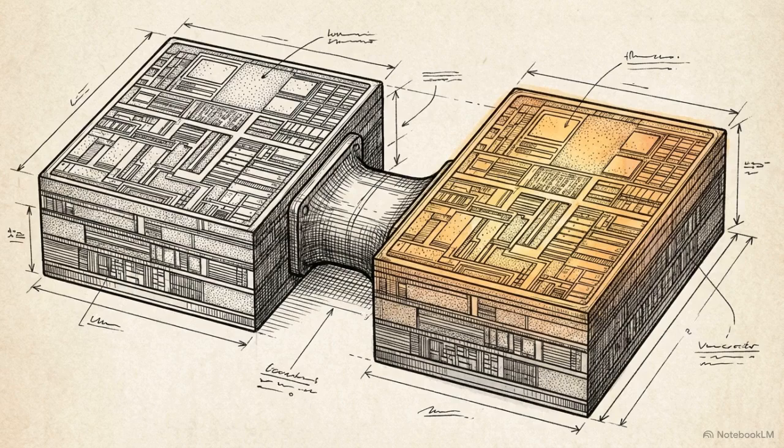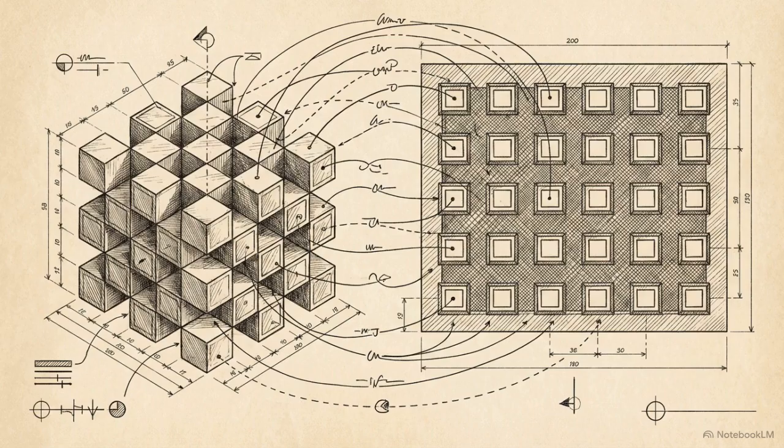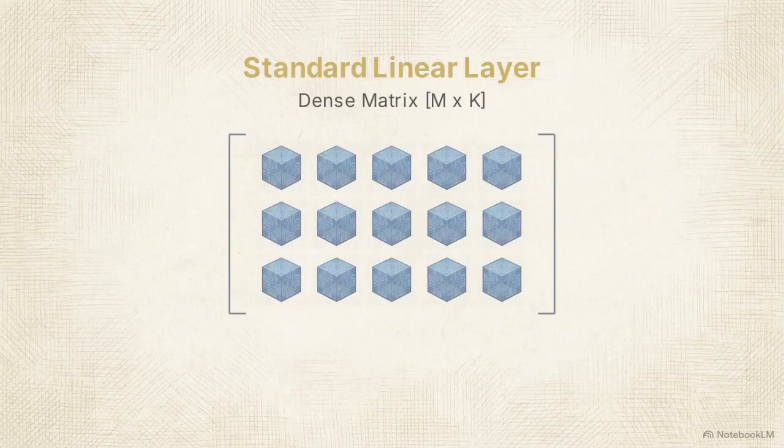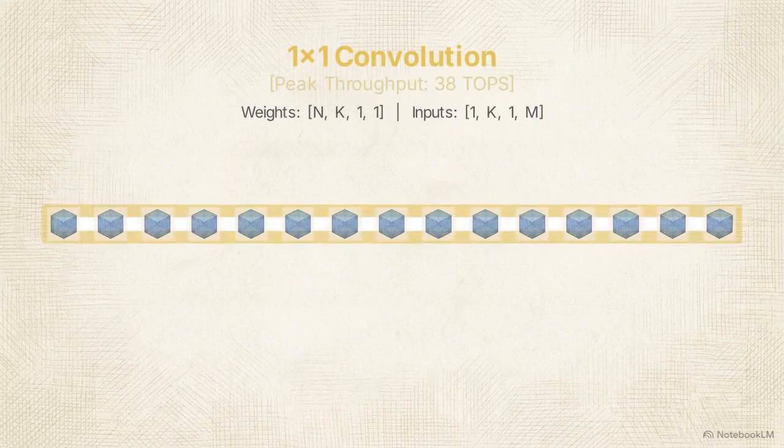Addressed directly, the ANE operates as a decoupled zero-copy graph execution engine, functioning as an independent coprocessor alongside the GPU. Accessing the private API exposes developers to a minefield of undocumented hardware limitations. The defining architectural truth of the ANE is that it is a convolution-first engine, rather than a generalized matrix multiply unit. To achieve peak throughput, standard linear layers must be mathematically reshaped into one-by-one convolutions.